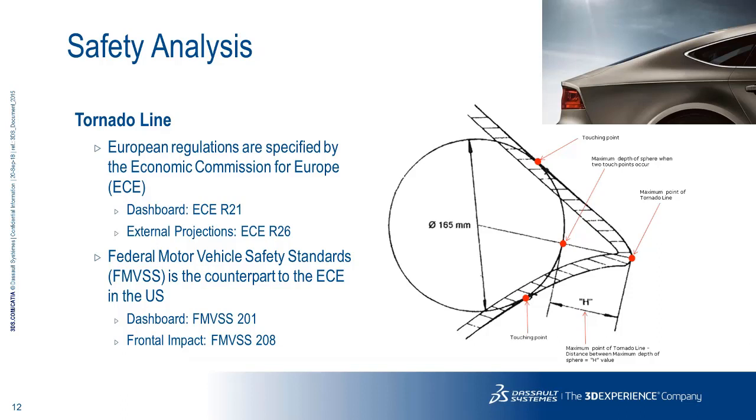So what is actually going on here? It's a little complicated, but I'll try to explain. Taking the 82.5 radius sphere, because it's the standard measure we like to use, we're pushing it on the inside of the tornado shape. So this V shape you see, this is the tornado, the feature line, and on the inside we're pushing the sphere.